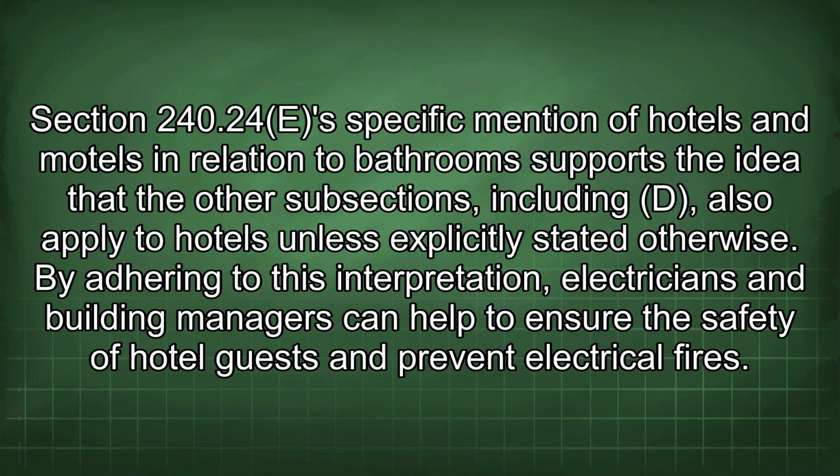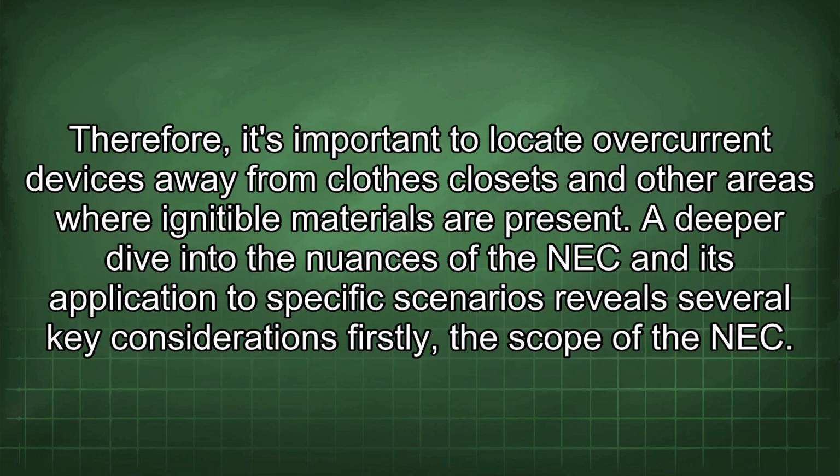Section 240.24(E)'s specific mention of hotels and motels in relation to bathrooms supports the idea that the other subsections, including D, also apply to hotels unless explicitly stated otherwise. By adhering to this interpretation, electricians and building managers can help to ensure the safety of hotel guests and prevent electrical fires. Therefore, it's important to locate overcurrent devices away from closed closets and other areas where ignitable materials are present.